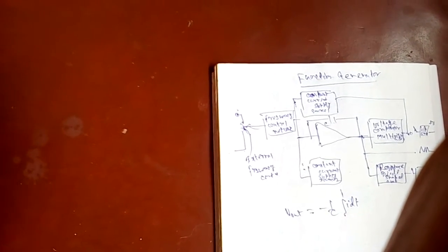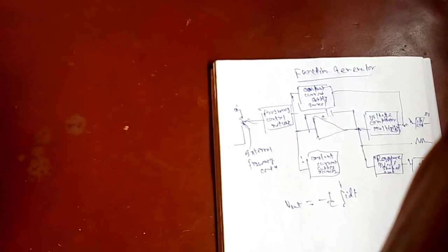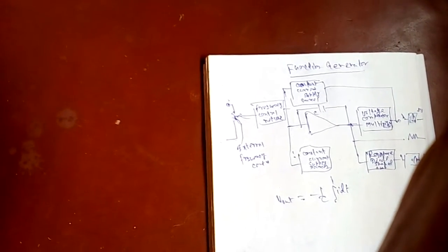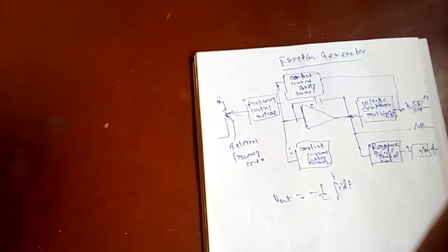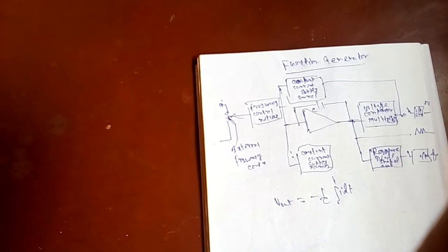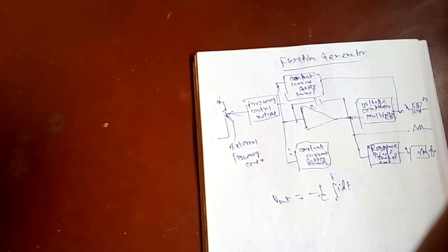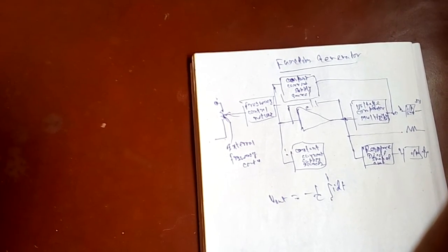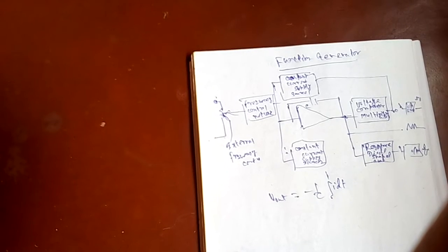The voltage comparator multivibrator changes state at a predefined maximum level of the integrator output voltage, and the current switches to supply source 2. When the output attains a predefined level, the voltage comparator again changes state and switches to supply source 1.